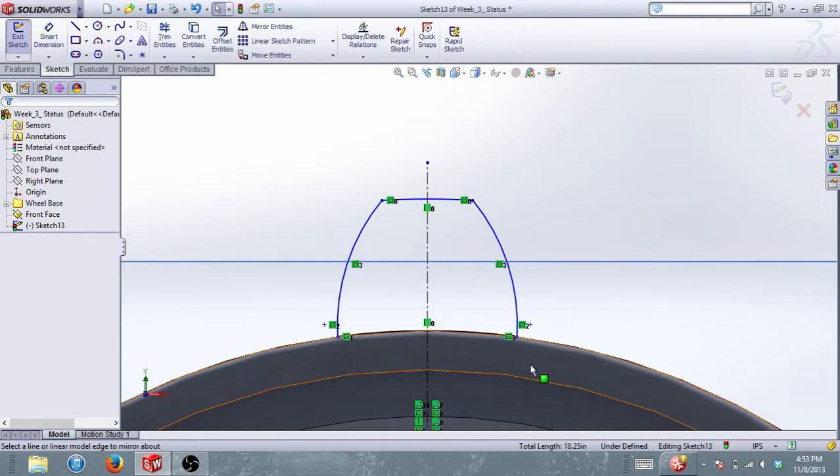Down here, you also have the compass for the bottom part. The reason I grabbed the bottom part is because I wanted to close the sketch. The reason it's small at the top is because of the mirror. If I reduce one side, it reduces the other. That's the purpose of it: you don't have to change two dimensions, just change one, and the other side follows.